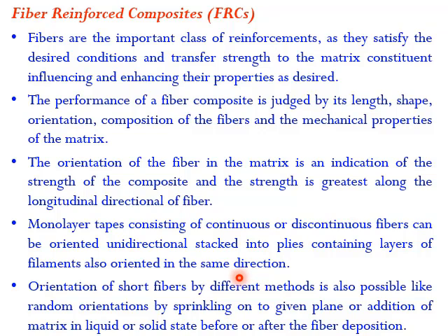So if you want the strength of a composite material in one direction, we can have fibers aligned in one direction. Or if you want strength in all directions, then we can have plies of fibers which are oriented in different directions, and then they can be formed, so in a bidirectional arrangement, to give strength in all directions.